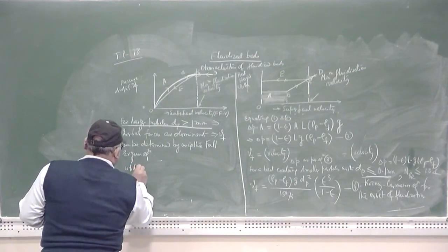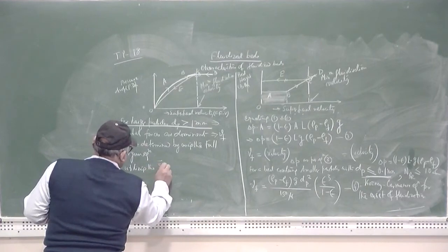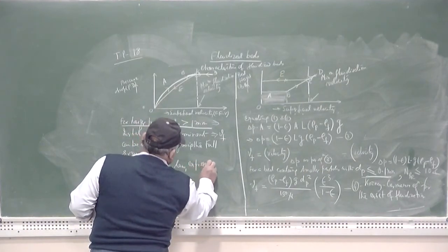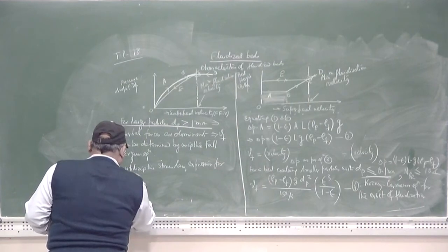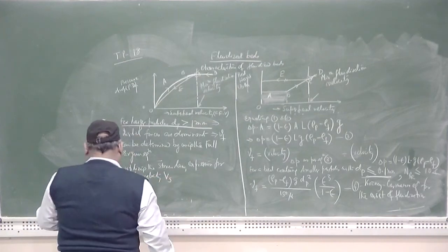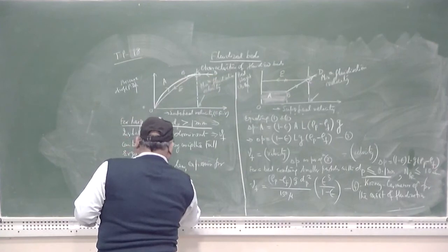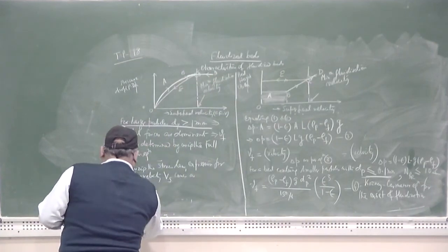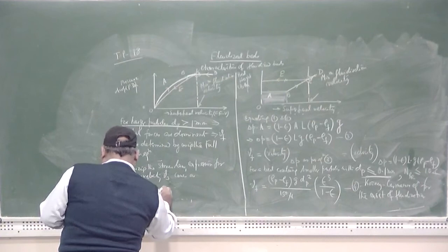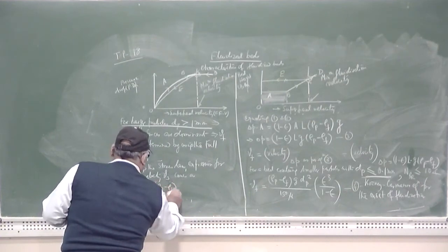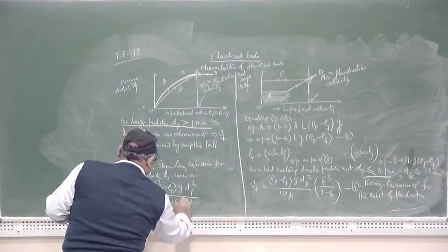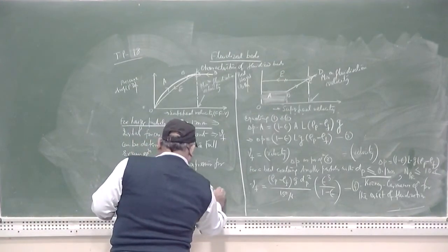Now, utilizing Stokes law, the expression for settling velocity, small Vs, comes as (rho p minus rho f) into g dp square divided by 18 mu. Let it be equation number 5.